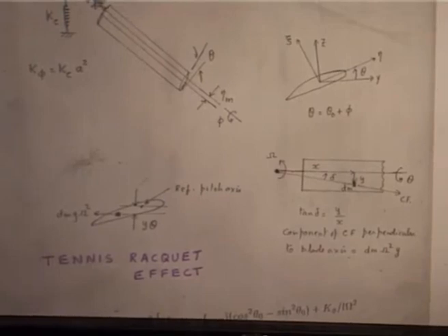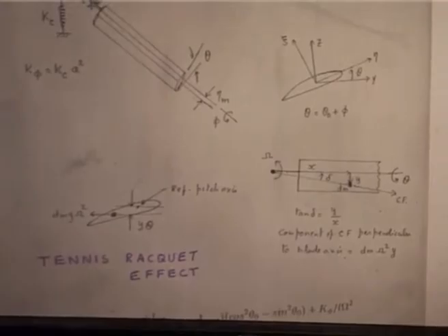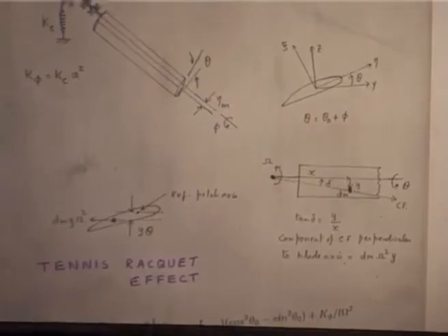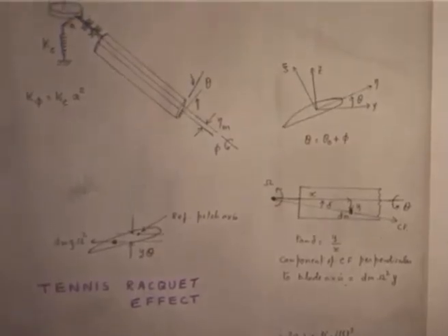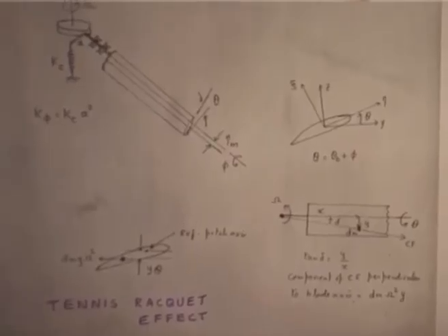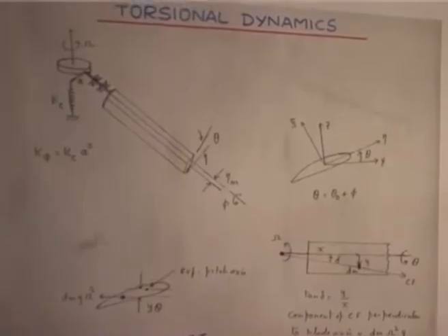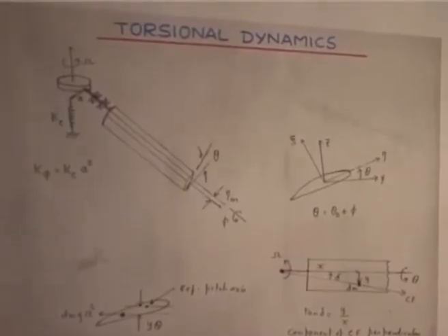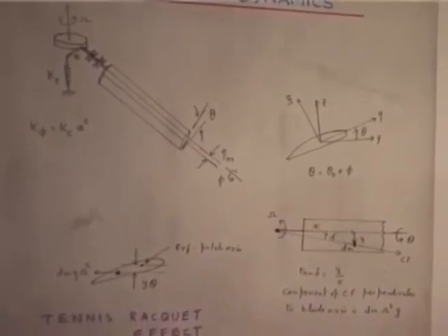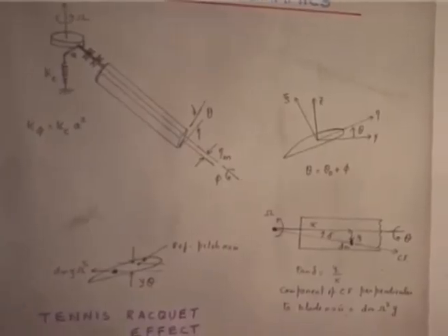Test data for I think 5 degrees or 6 degrees, 6 degrees, 900 RPM you are matching. When the RPM went up, you find that with a pitch angle of 6 degrees you are getting 60 Newton or 61 Newton, but what was observed was only 52 or 53 Newton. But why that big difference? Okay. You will see slowly that it may be due to this reason.